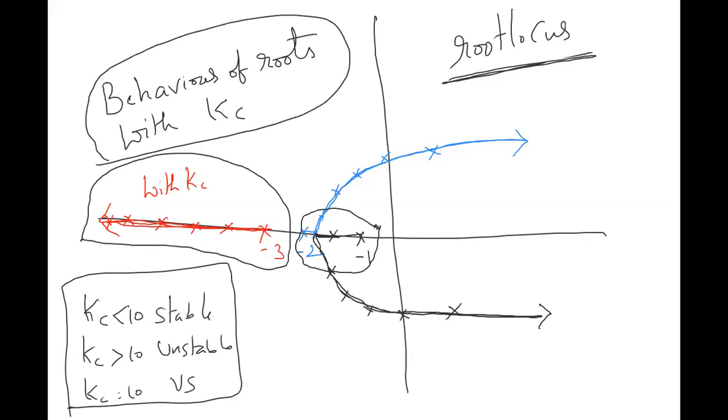Even this Kc equal to 10 you will not use in the plant, because this Kc equal to 10 is coming from the models. Models may not be accurate. So these models are showing that Kc equal to 10 is the one where the system goes to the unstable region. But in reality, maybe the models may not be right. That is why, even though I have the flexibility of going to Kc up to 10, you will lock at 5 itself.